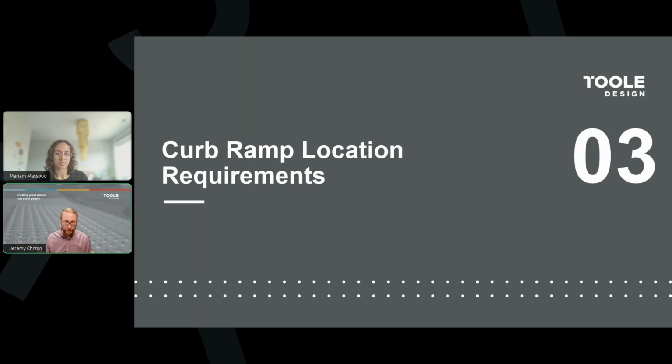In the published version, they removed right-of-way as a physical constraint. So if your project is already doing right-of-way acquisition as part of its scope, even if it's not at that specific location, then it needs to be evaluated whether right-of-way needs to be acquired at that corner. If right-of-way acquisition is not part of the project, then the right-of-way lines are the constraints and require us to still be creative about how we can provide either a compliant or as compliant as possible curb ramp.